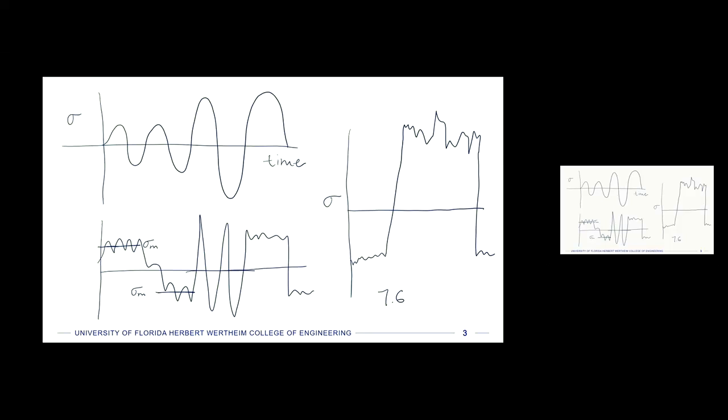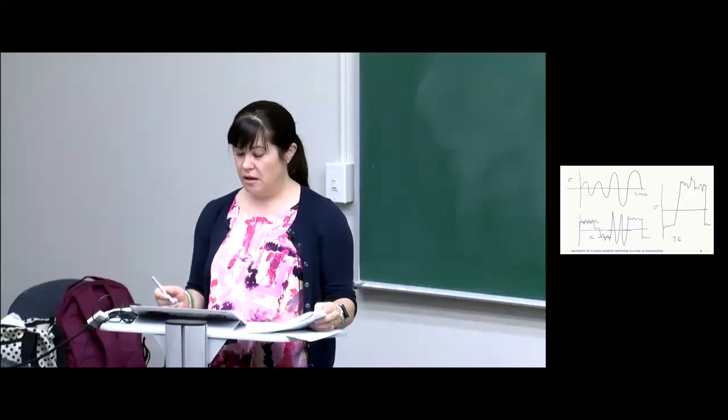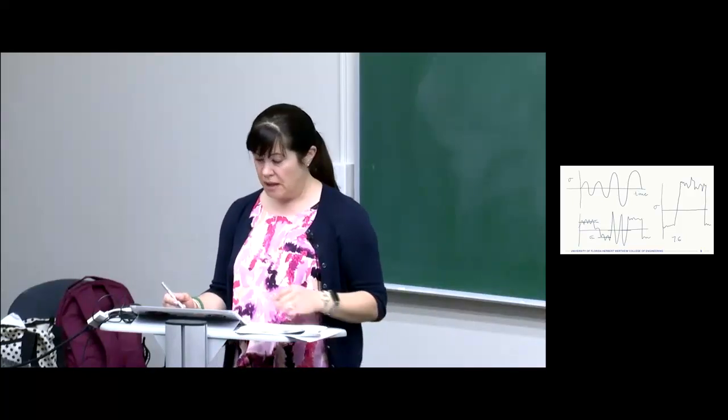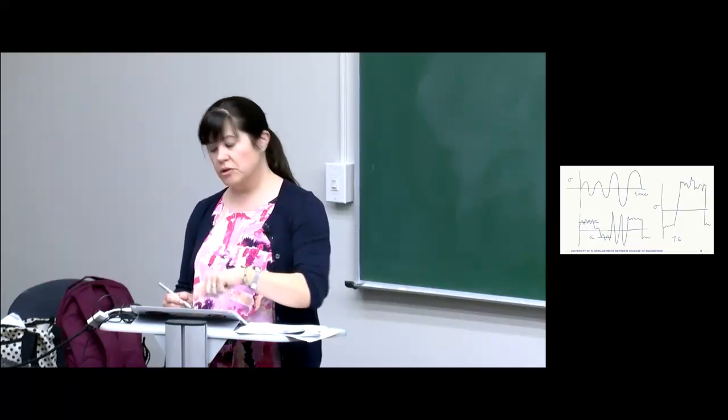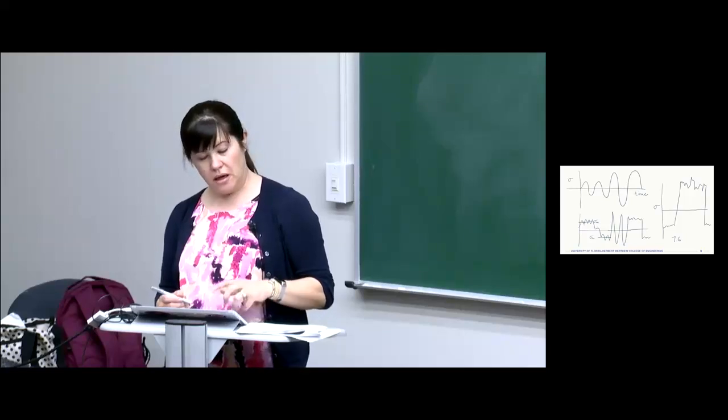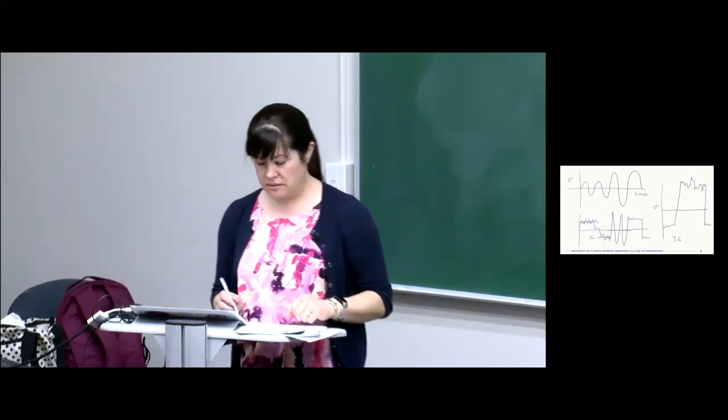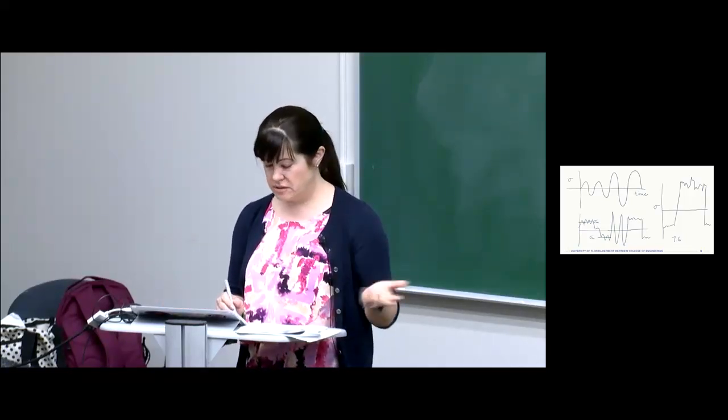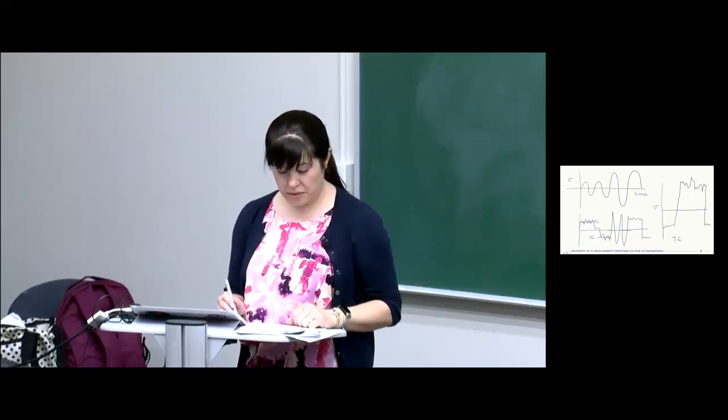And then when the mission is ending, the aircraft lands, the lift is no longer on that component, and it goes back. If this is for a typical mission, then you would add this up many, many times, and that's what the life stress profile would be for a particular component. So we'll talk about damage accumulation, and we're going to start with just fatigue and completely reversed constant amplitude loading.